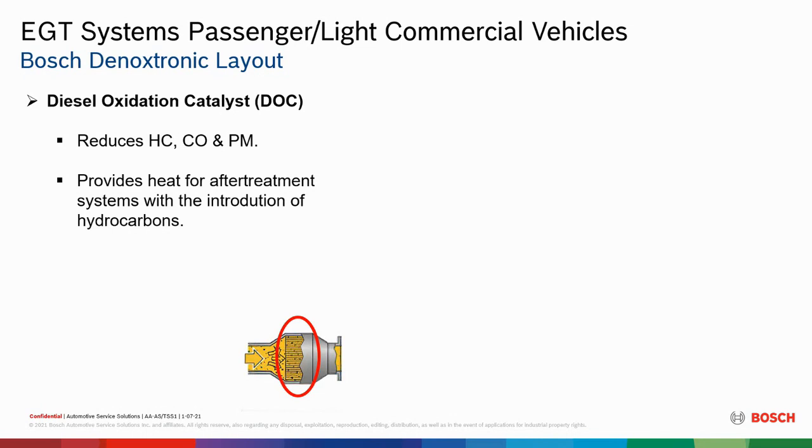We get calls from brand new vehicles that have DEF and gasoline contamination continually. I don't know how people do this, but it happens. I guess it's good job security for everybody in the diesel world, but it does happen. So those are things to watch out for: damage to the DOCs or the pre-DOCs as well.